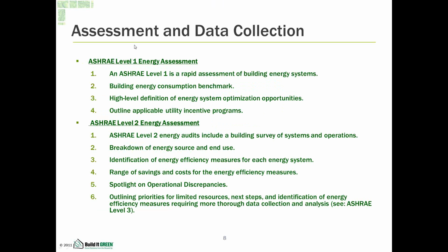The type of assessment data you're going to be collecting and receiving from your assessor is pretty much an ASHRAE Level 2 assessment, and that is built off an ASHRAE Level 1 assessment. ASHRAE Level 1 is just a really general high-level overview of the building. The ASHRAE Level 2 is more of a survey and gets more into the systems and operations. It breaks down different end uses, and it identifies measures or what's wrong with the building shell or systems, HVAC systems or domestic hot water systems.